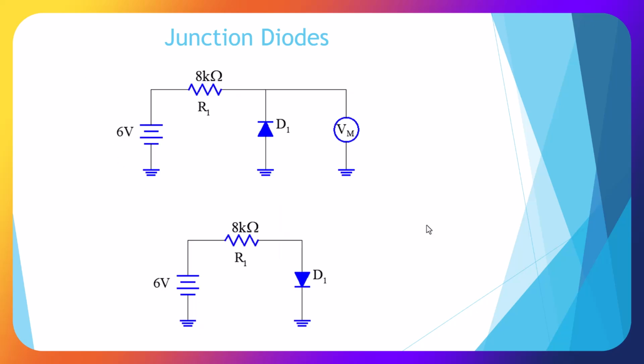Okay, here are a couple diode circuits. This diode is reverse biased. When it's forward biased, its arrow points towards ground. In this case, there is no current flow through here, so our current flows through our meter, and we're going to get 6 volts since it's essentially an open circuit through our meter. Here it is forward biased, so we're going to get our voltage, our diode with 0.7 minus 0.6. We figure out the current across our resistor to make sure that it's not damaged.